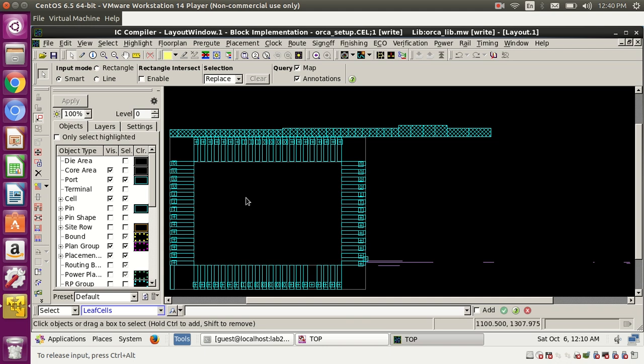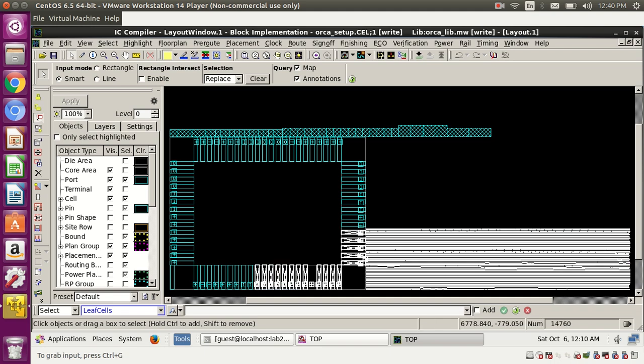So even for all the theoretical values, or in whatever interview you give answers, you only say whenever two nets are parallel. You just analyze why you say that nets have to be parallel. Why are you saying that? That is the thing: capacitance will come whenever they are parallel. So that's how capacitance is the input for the load.